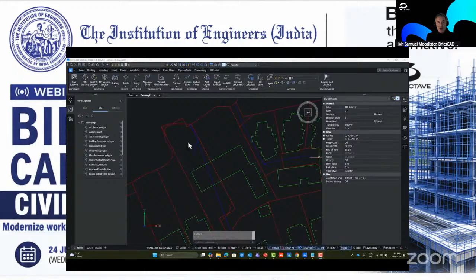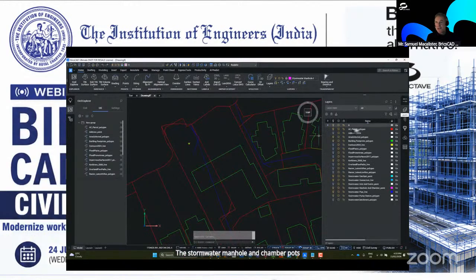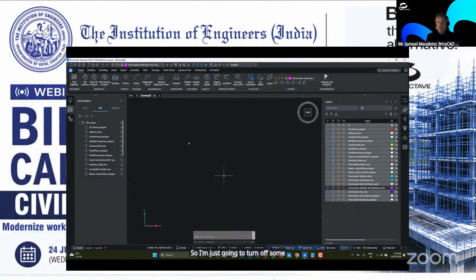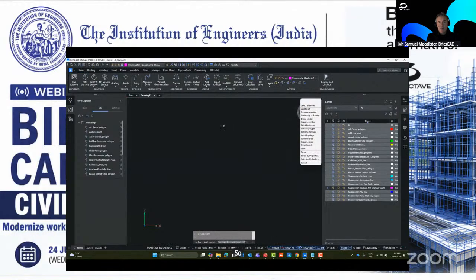So in this file, the points that have come in that represent the stormwater manhole and chamber pots are just shown as dots. They're very hard to see, and we want to convert these to symbol styles. So I'm just going to turn off some of the layers and grab those points and convert them to CAD points. So simply we go to create civil points, select all entities or grab them on the screen,